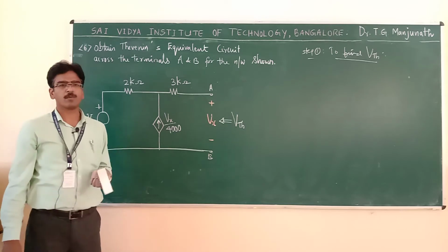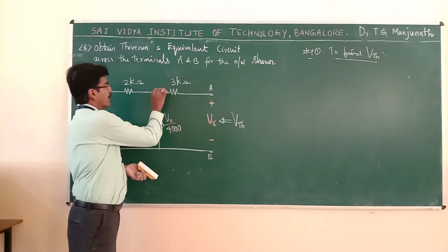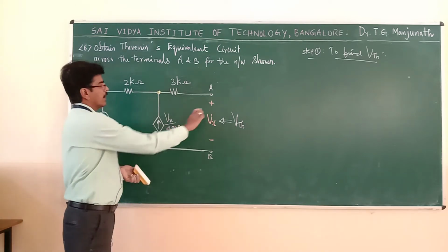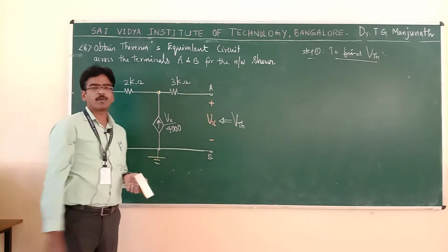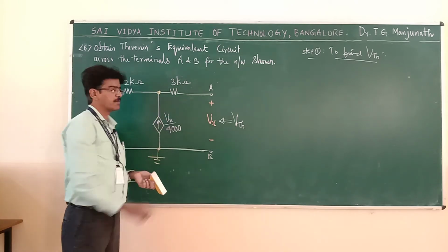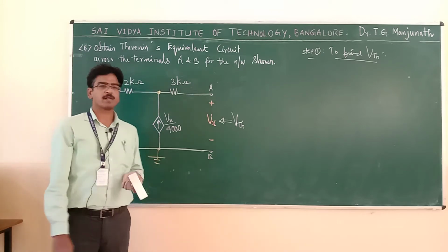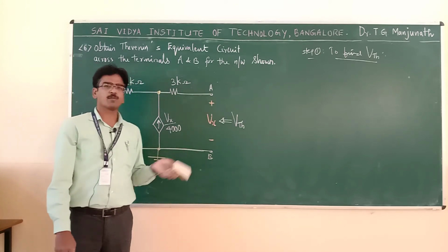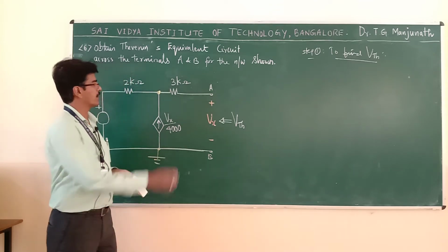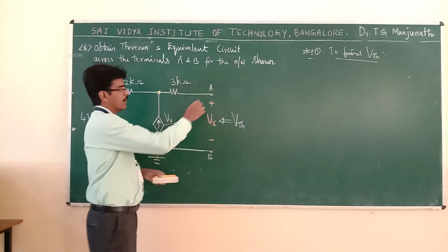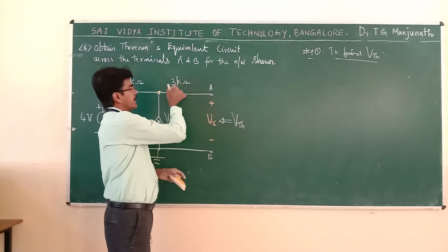Or if you want to go by nodal analysis, then you have this principal node, and you can take this as the reference node, because only one principal node can be taken in this problem. To measure the voltages in any network, I need one reference node. Hence, in most problems, the bottom line is considered the reference node. Then what is this voltage? You can see here, this is open circuit, so no current is flowing here.